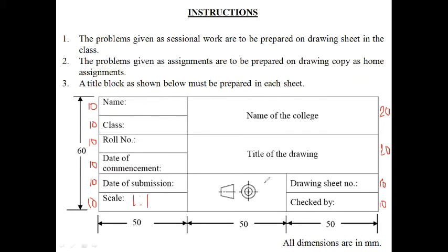Now, this is a figure you see. This is basically the figure of the projection. I will discuss the projection, and then the meaning of this figure. So how can you draw this figure? First, you take a small diameter circle, and another concentric large diameter circle. Clear? First, you draw this, and you take the measurement in such a way that it fits this area. And here you first draw a center line.